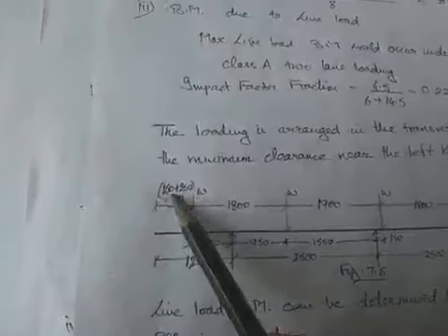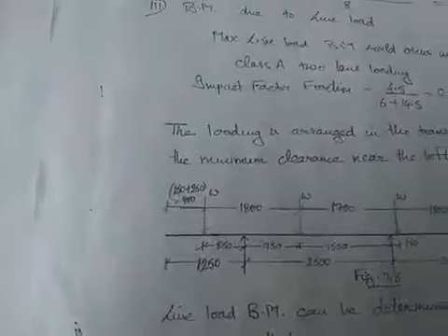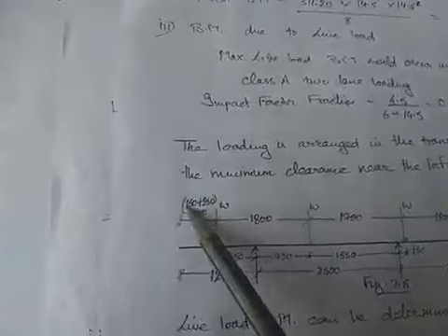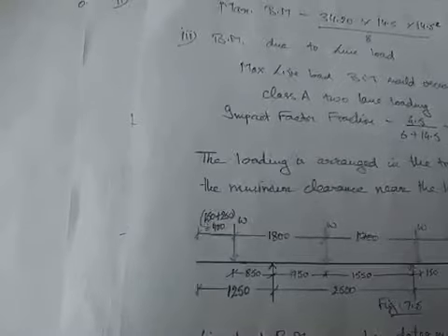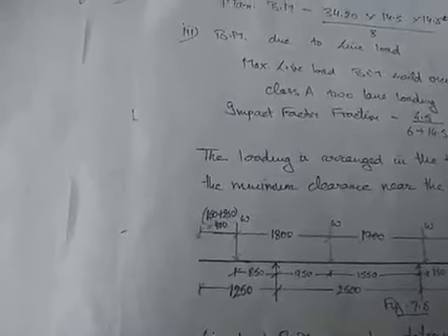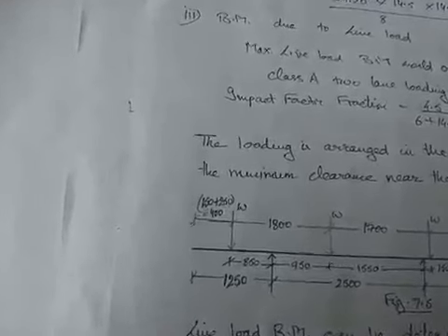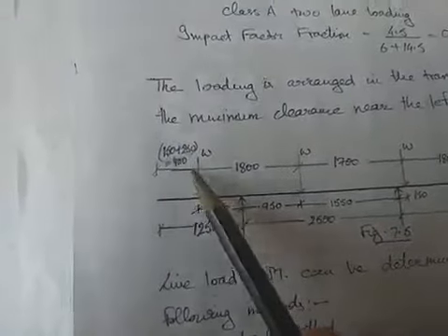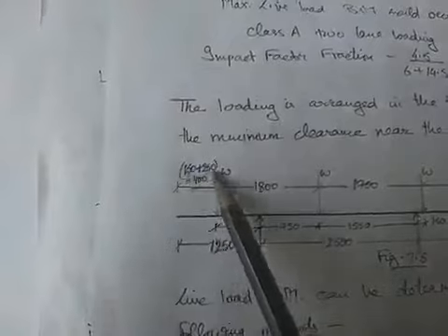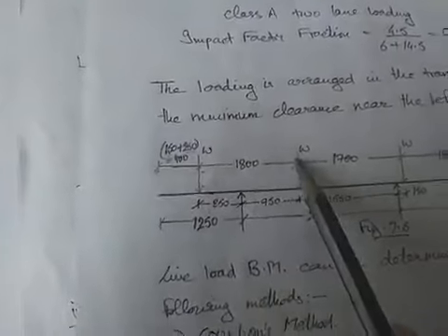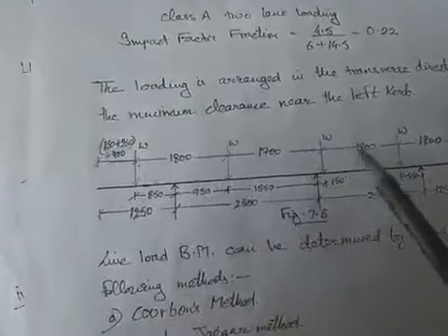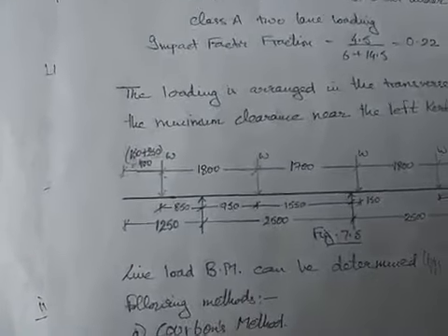You see it has a clearance factor of 150, and then it starts at the center line where you have a width of 250. So this distance is 400. I repeat, clearance is 150, then the width of the tire is 500. That is why it has been taken as 500. The severe case has been taken up, so that is why you're getting this distance as 400. This is the line diagram, and there you have the width as 500, so half the width has been included in here, so this is 400. Then again center to center it is 1800, 1700, 1800 and 1800. So this way you have the W as the loads. So these are the severe loads.